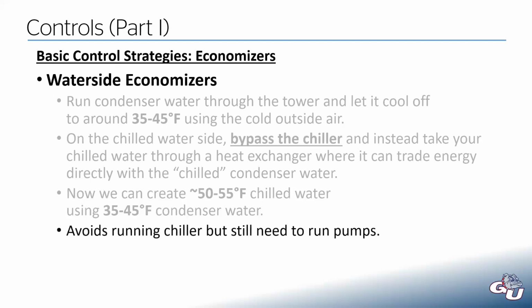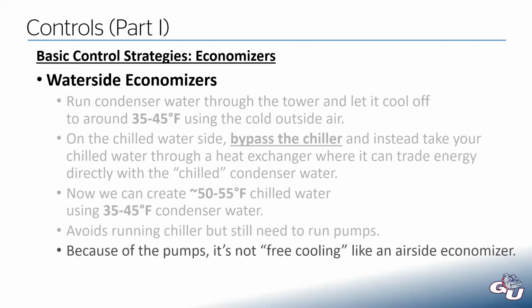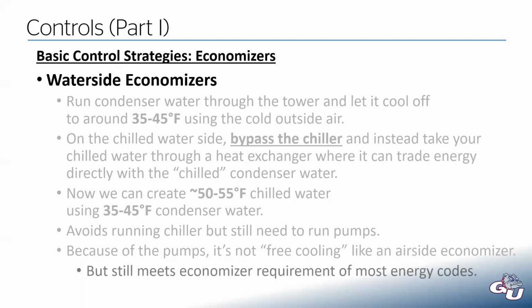This does avoid running the chiller, but you do still need to run all of the pumps. You still need to move all that water through your system. Because of that, because of those pumps, you can't really call this free cooling. In an air side economizer, you can, because all we're doing is running the fan and just introducing more air, no penalty there. Water side economizer, you're still running pumps, so it's not quite free. But most energy codes say water side economizers are good enough.